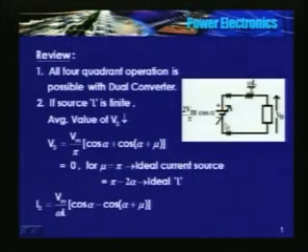This is the average value of the output voltage drop due to the source inductance, the load voltage V0, and here there are 2 thyristors because in a single phase bridge 2 devices are conducting at a time, and we found that V0 is 0 for mu equal to pi. It is possible only if the load is an ideal current source.